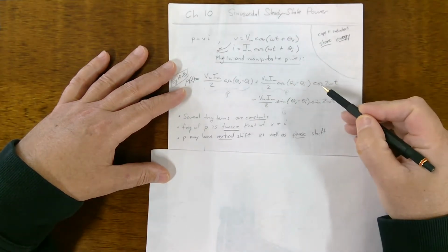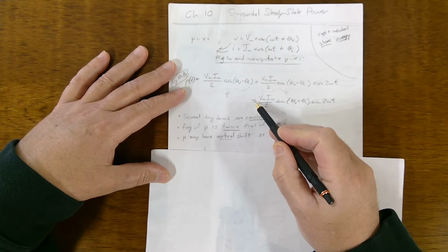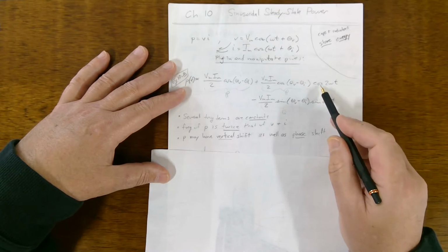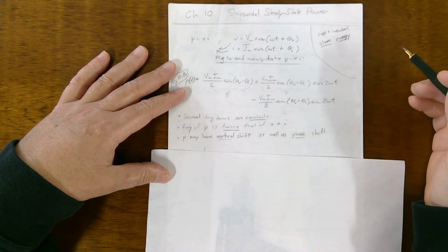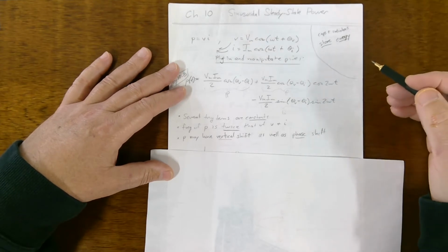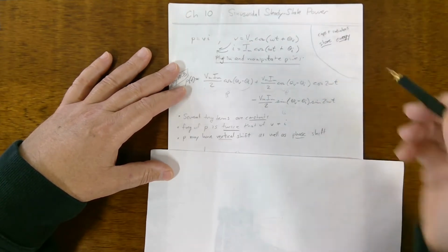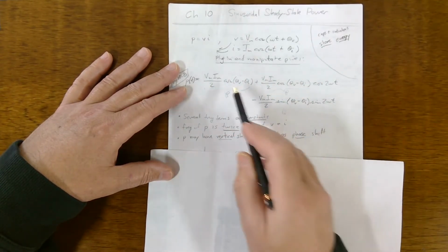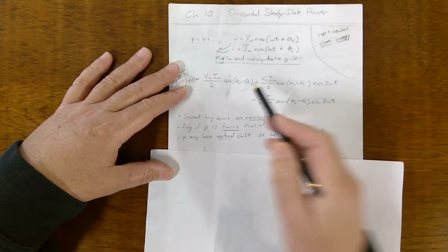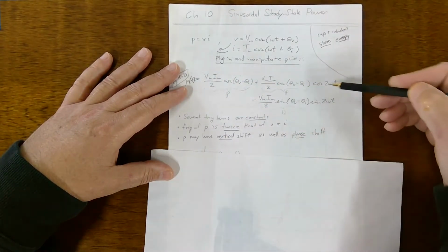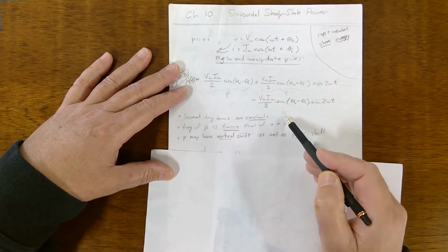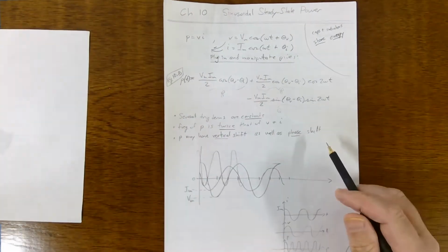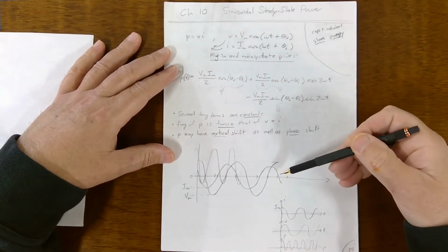Remember, there's a cosine and then we're subtracting a sine. A cosine minus a sine is just another cosine function with a phase shift. So they're hiding the phase shift, but it's convenient to look at p of t in this form, broken up into a constant P term times a cosine function, and a constant capital Q term times a sine function. It's just convenient. And bottom line, time domain wise, this is what we're looking at.